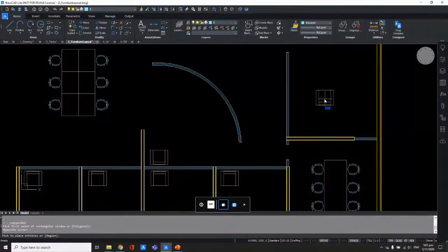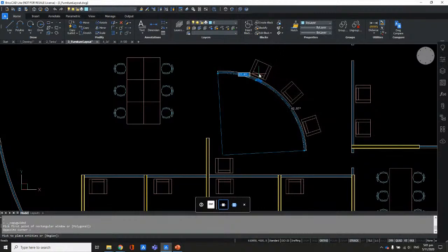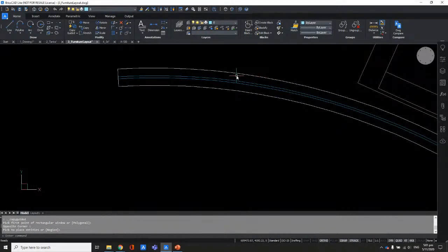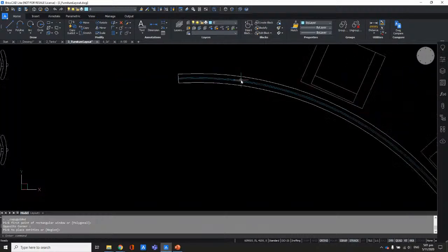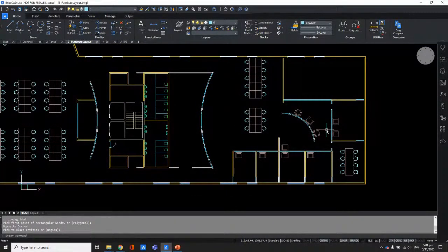It also recognizes base curves that are in a different direction. So let's put those there. And it also recognizes actual curves as long as your base curves are modeled out in the same manner. BricsCAD should be able to read that. And on top of copy guided, there is a new feature with V21, which is move guided.